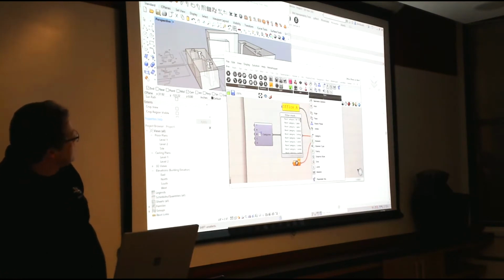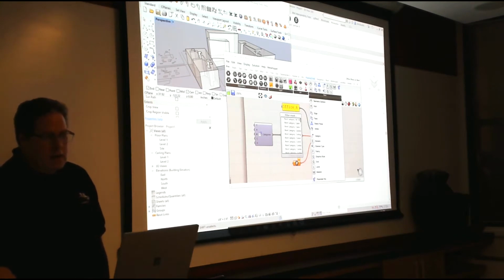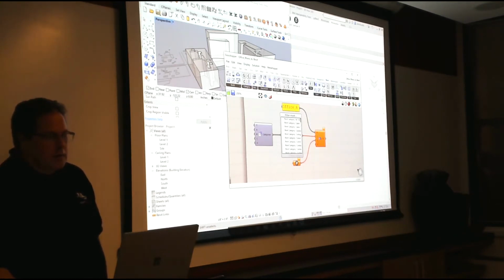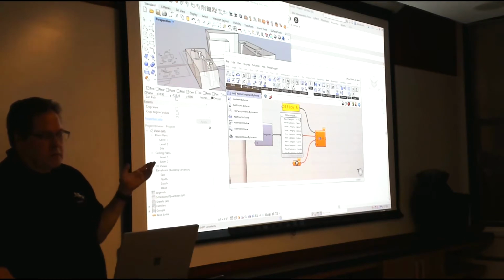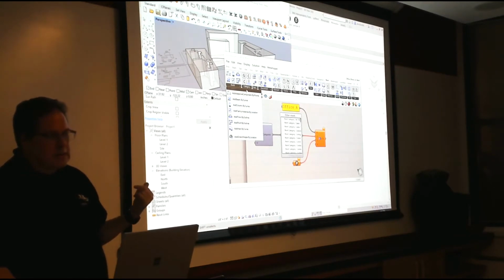But Grasshopper creates Revit-aware toolbars that you don't see normally. So we have a geometric element, a Revit edge, a Revit face, a Revit category, and element. These are some inputs you can have. It also creates a Revit toolbar that does things like create adaptive components, create system families of objects, create walls, put family instances in. We can interrogate categories. We can create grids. And this thing that I heard is pretty important to Revit called levels.